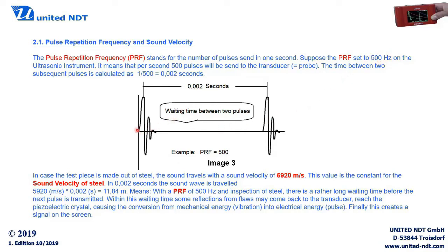And what you see here, by the way, is the type of pulse: how it goes up to a high amplitude, then a low amplitude, and it goes up again, but not to the same height. That means there is a certain damping. The pulse is not going for a long time. There's a damping material behind the piezoelectric element, which damps the pulse after receiving the first electrical pulse. So it's a rather short time, it comes down and reaches almost the zero line.